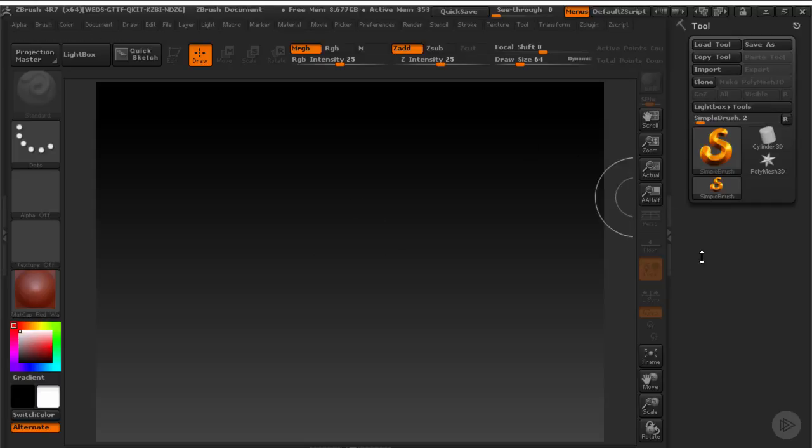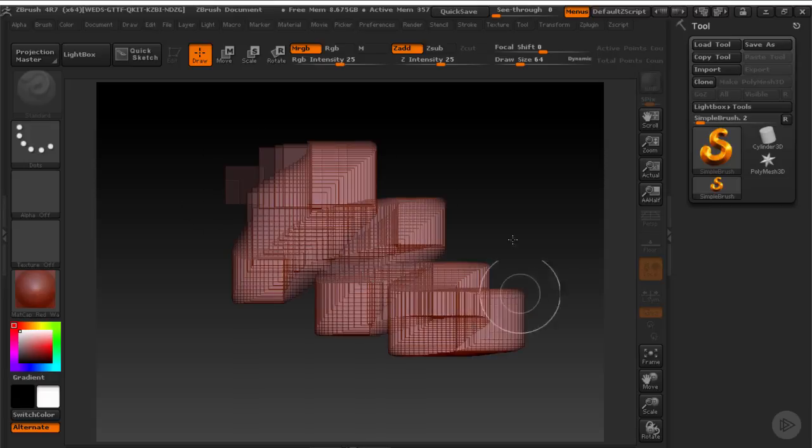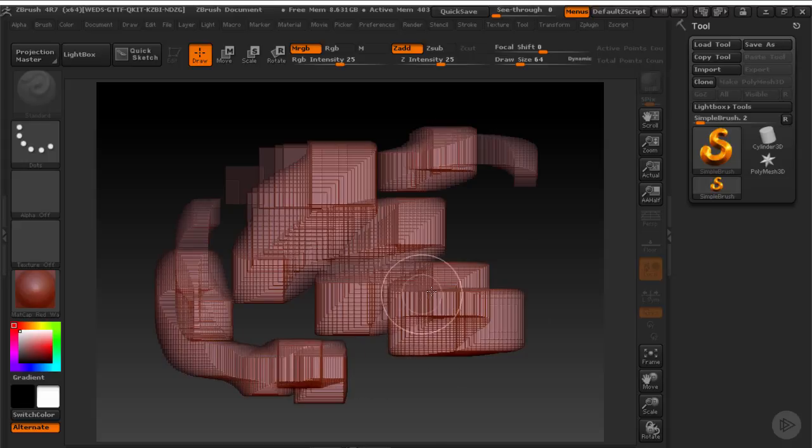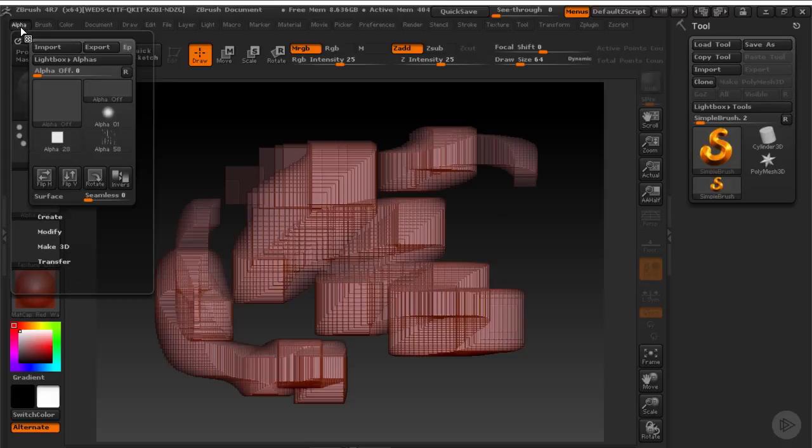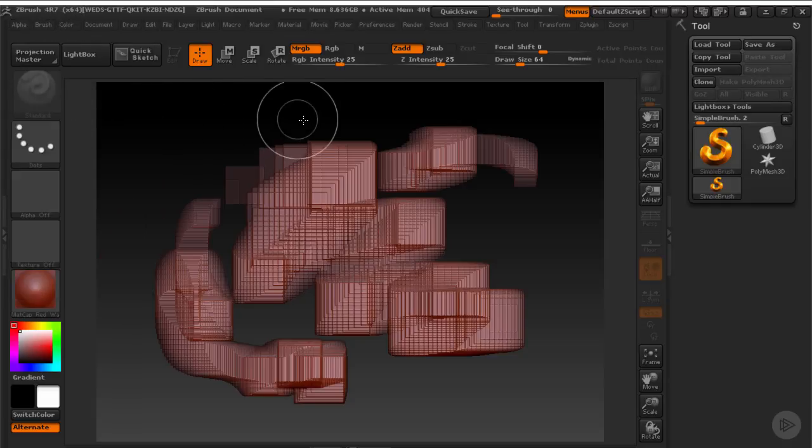All right, so we've got the ZBrush interface here right now, and it may look pretty intimidating, and to be honest, it kind of is. The user interface itself is a little bit not terribly obvious. For example, if you start trying to paint right away, we're not really dealing with a 3D model. We're dealing with this weird 2D space that exists inside ZBrush to begin with, which is not really what we want. Also, if you scroll up to the top, we'll start seeing Alpha as the first thing that we have to click, as opposed to things like File and the sorts of options that we're pretty used to in most applications. So where we actually want to start is over here in the Tool section.